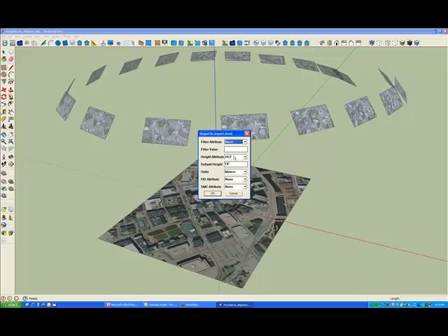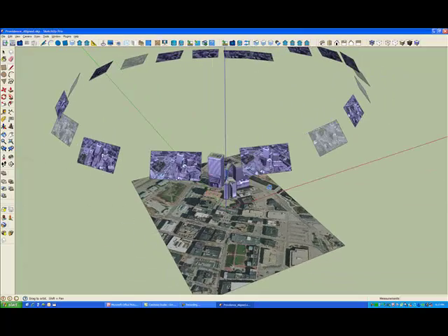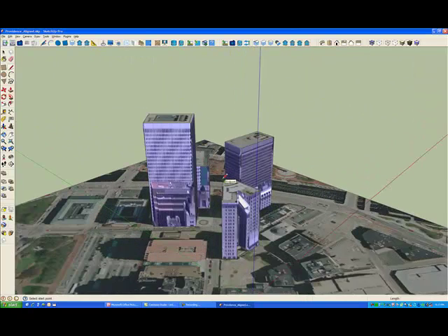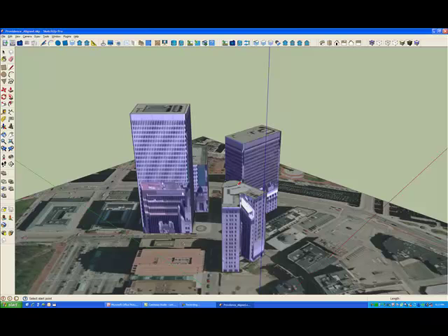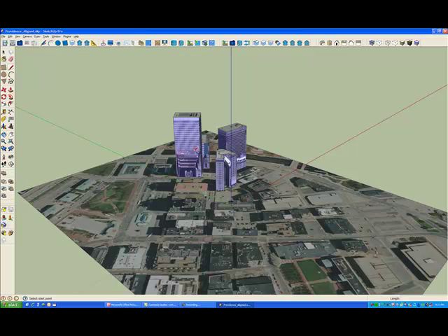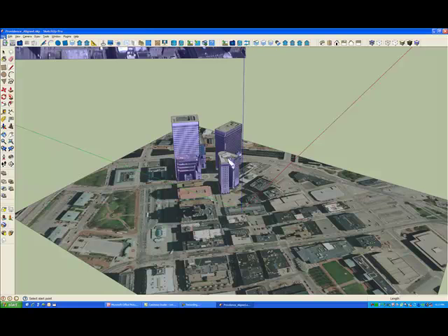And it reads the attributes that are in the shapefile, and if there is a height attribute, it'll find that, and we can select it from a drop-down list, and we just need to specify the units for the height attribute. In this case they're in feet. We have the ability to filter by attribute values and to pull in FID and SMC values from the attributes. And then it'll read in the footprints from the shapefile and construct the geometry from the height information. The top face is textured from the nadir image, and the side faces are again textured from our oblique camera images. And we have that same problem of the obscured building, but we can use that same technique to fix it.